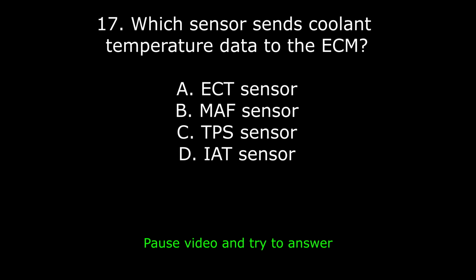25. When servicing hybrid AC systems, what special oil must be used? A. PAG. B. Ester. C. ND11 or equivalent non-conductive oil. D. Mineral. Answer: C. ND11 or equivalent non-conductive oil. Explanation: hybrids require non-conductive oil to prevent high-voltage shorts.